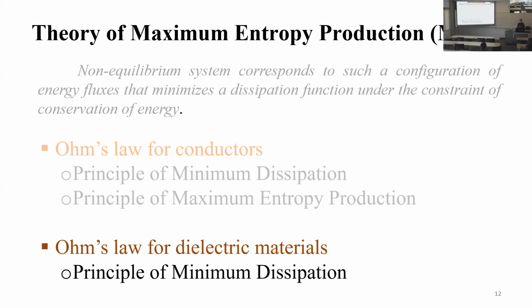I want to generalize Ohm's law to dielectric material. So Ohm's law is for conductors. Now we want to generalize to non-conductors, which are called dielectrics. Everything else is dielectric, so non-conductor. That's what we need to study radiative transfer through soil, through vegetation, through other natural material, for remote sensing.